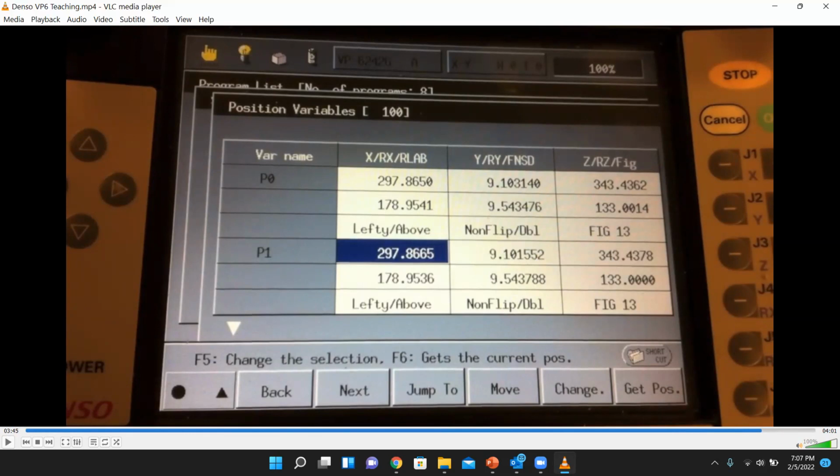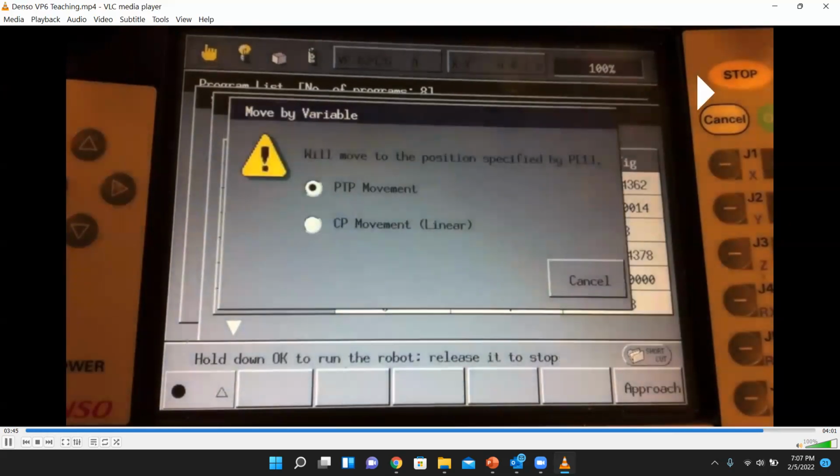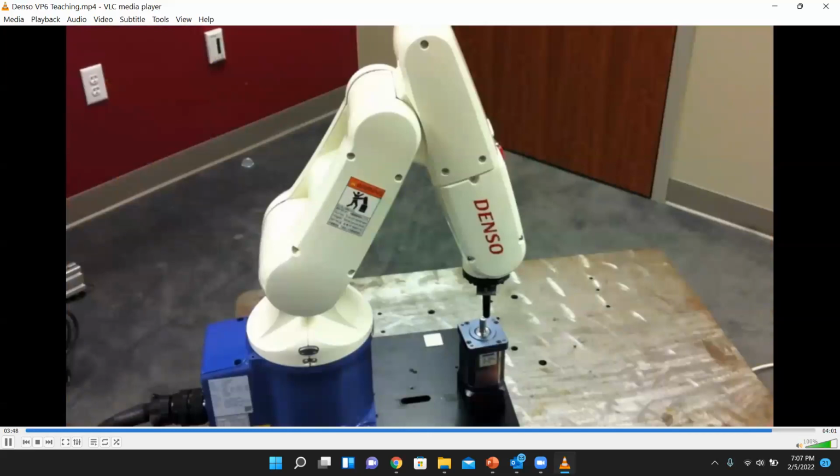So when you have a number of points like that, P0, P1, P2, P3, P4, and you have set the speed also, the controller can actually interpolate all the joint angles from point 0 to point 1, point 1 to point 2, point 2 to point 3, like that, and then create the reference trajectory as I explained earlier, and then take one at a time and implement it and send it to the servo controller for implementation. If it requires the end effector to travel outside of a linear path.